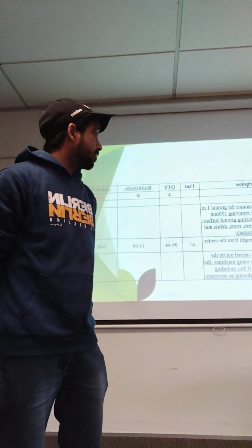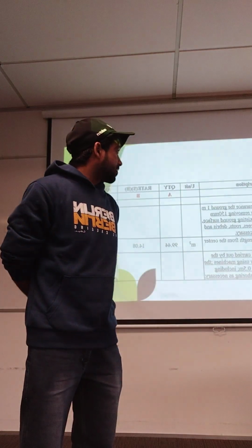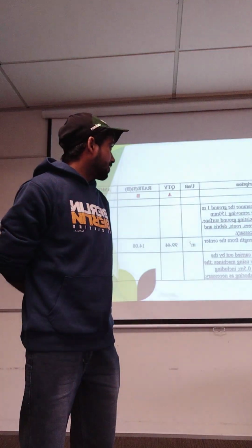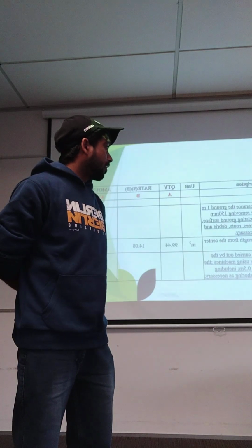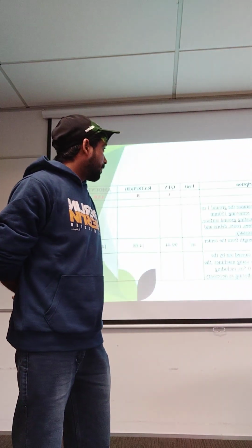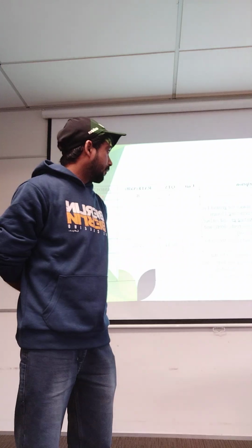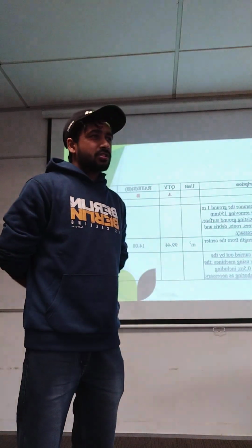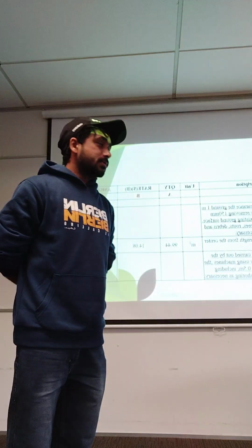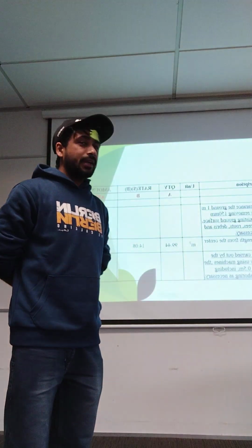Next is preparation of the schedule of quantities, which includes earthwork and ground clearance. The contractor has to measure and clear the ground 1 meter away from the grid, by removing 150 millimeter topsoil layer from the existing ground surface, not limited to that. Remove trees, roads, debris, and other obstructions which disturb our construction. We have to clear the ground 1 meter length from the center line.